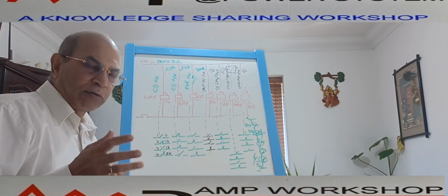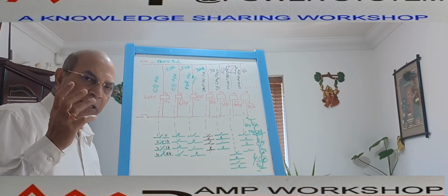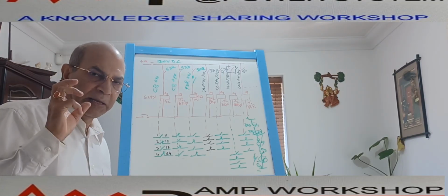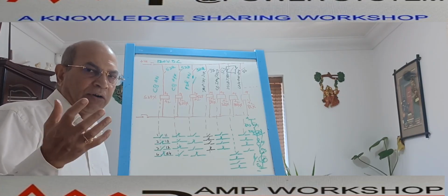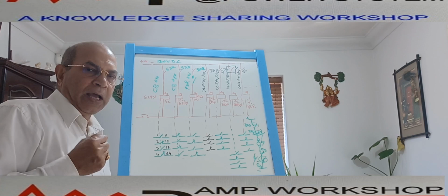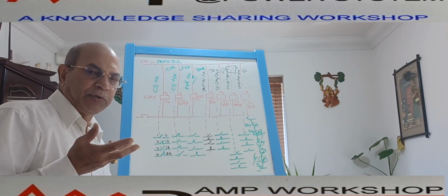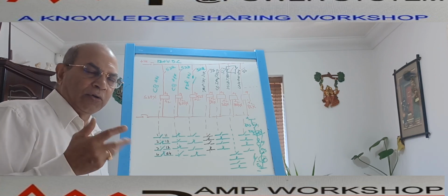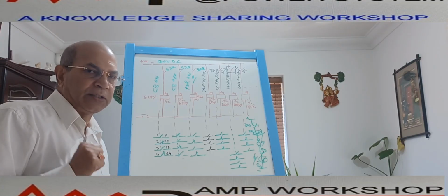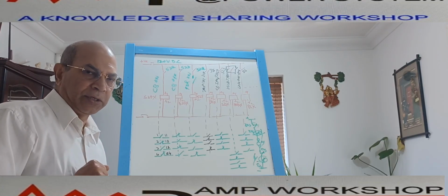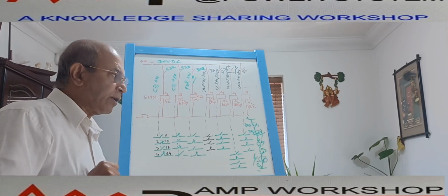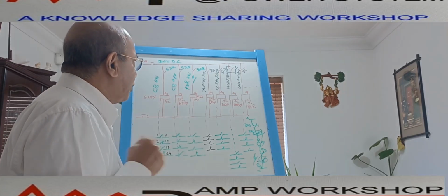In the spring charged condition, there are limited contacts, maybe 2 contacts or 3 contacts or 4 contacts available. And in the spring not charged position also, there are 2 or 3 contacts available, in both NO and NC combination. So there is a limited number of contacts available in the case of spring charge.